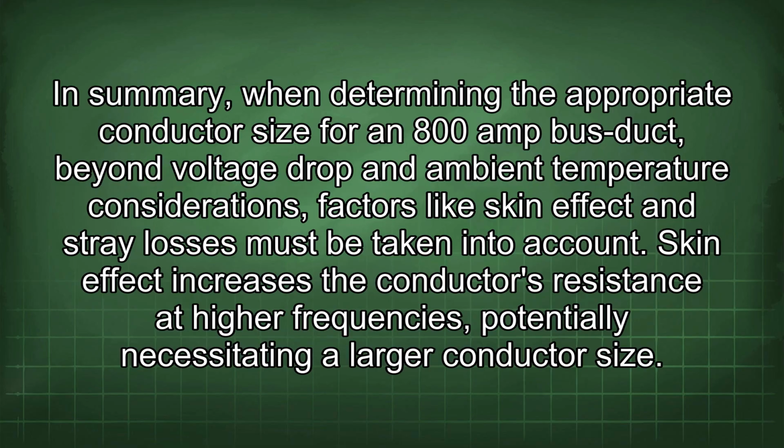In summary, when determining the appropriate conductor size for an 800-amp bus duct, beyond voltage drop and ambient temperature considerations, factors like skin effect and stray losses must be taken into account. Skin effect increases the conductor's resistance at higher frequencies, potentially necessitating a larger conductor size.